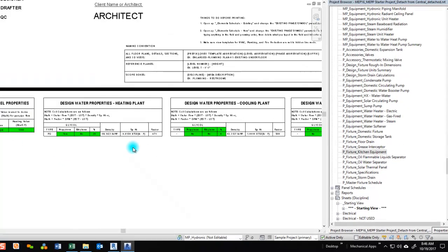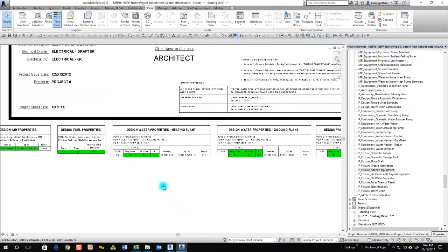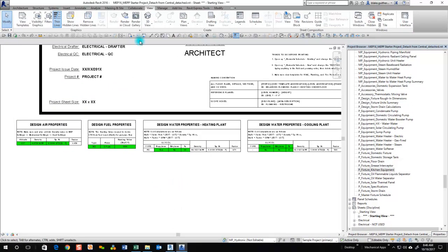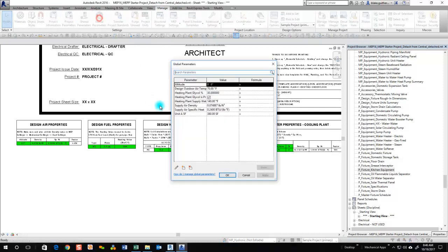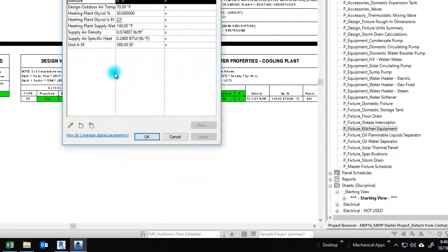The main reason is because Autodesk offers one solution and it just wasn't the perfect fit. Autodesk does offer global parameters here, and you can make a parameter, and you could edit one value here. However, this parameter needs to get tied to every family, and you can't tie it to the family until the family is already placed because it has to be an instance property. So that would have created, I think, a lot of inconsistencies in the designs.